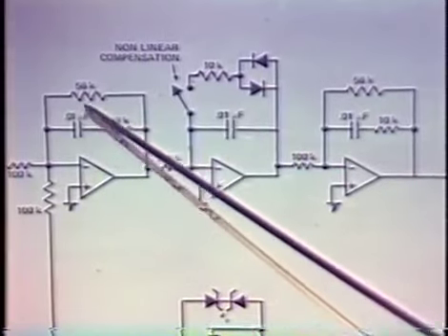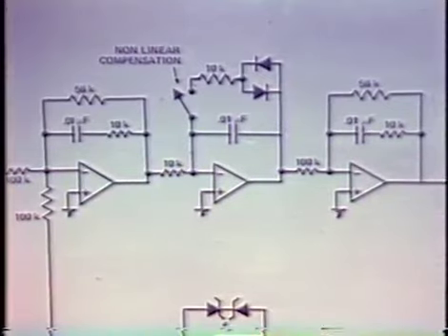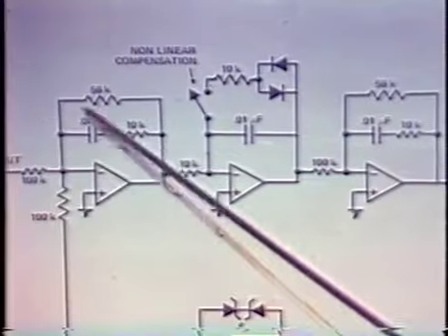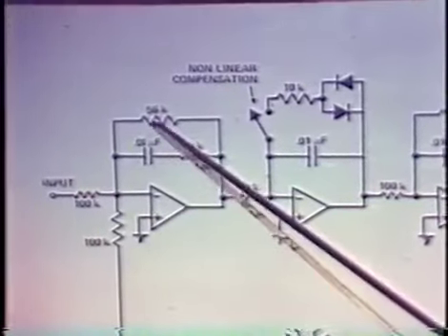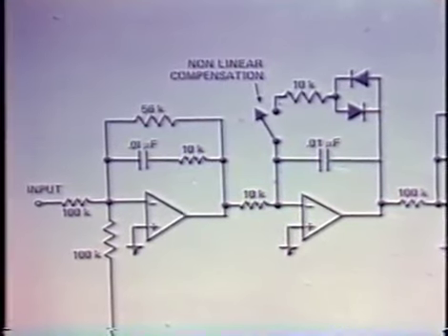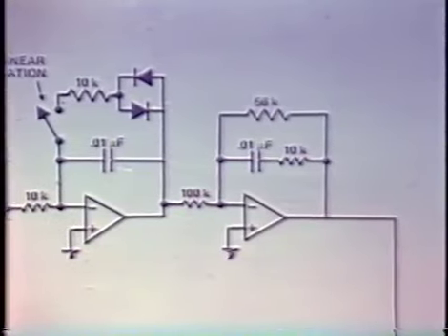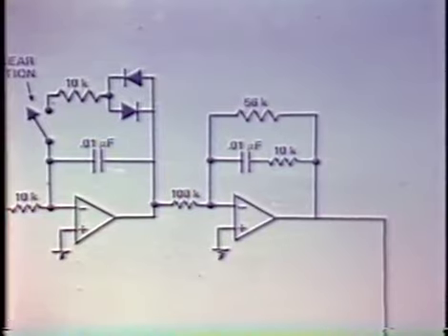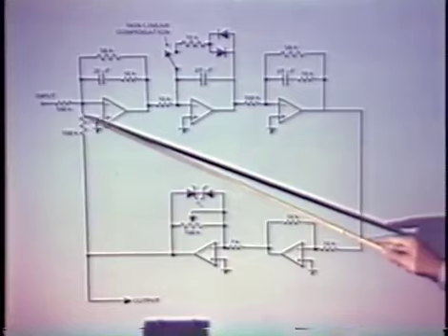And here we have the 2 operational amplifiers that give us the lag-type transfer functions. At low frequencies, the gain of the amplifier is 0.56. At higher frequencies, it decreases by a factor of 6.7 if you keep track of everything. We have another really identical network here. We have the input to our system. This is really the feedback path. We consider this the output of the system. So this resistor provides the overall global feedback path.